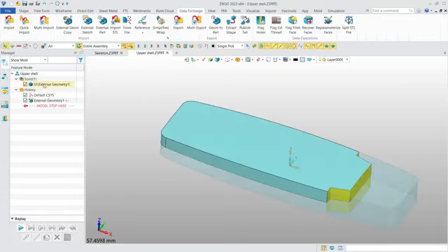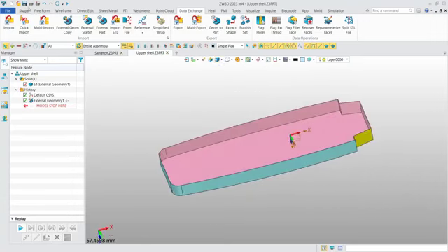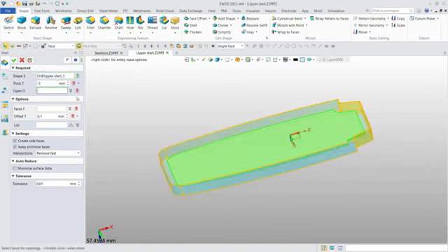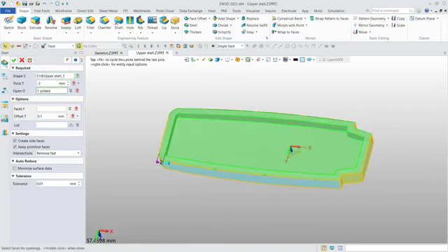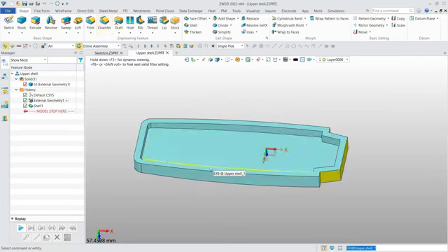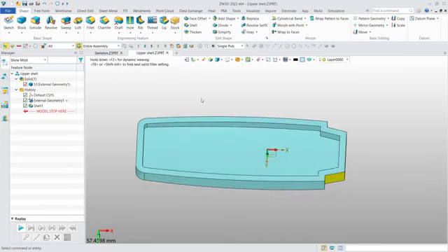For example, upper shell, we can something like add the shell and open. Okay, and then you can do more detailed design like the fillet, chamfer, and some other structure you can add it. So I will not go very further here because this is all about the modeling functions.